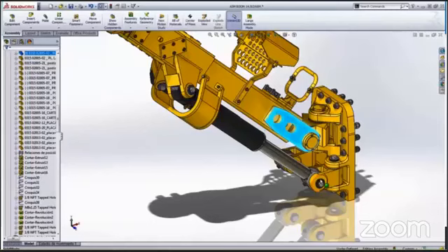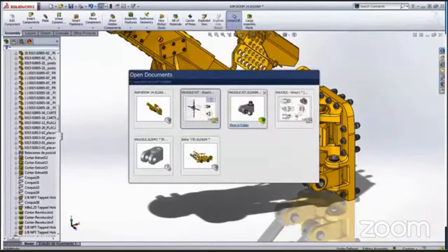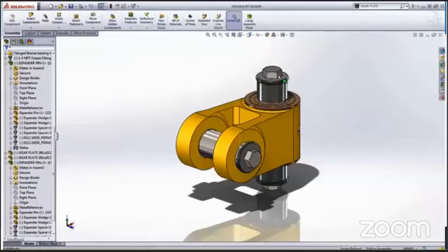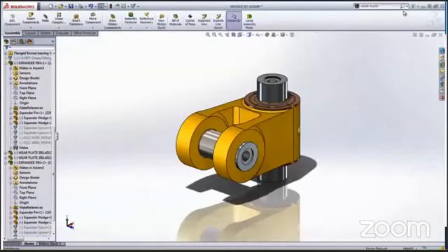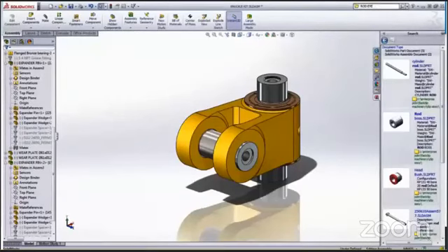The 125 millimeter bore hydraulic cylinder puts out a great deal of force. In order to validate our design, we should perform a simulation on our knuckle kit to see if it can withstand the load. To do that, we will leverage SolidWorks Simulation, and also these bolts and washers. This can be easily accomplished with the selection tool as well.